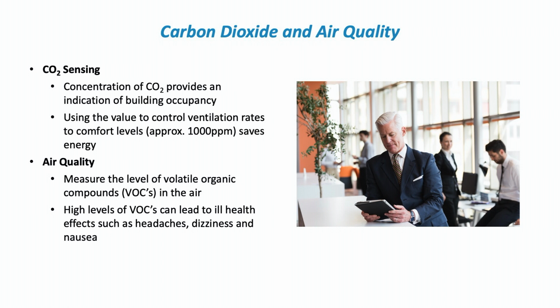CO2 sensing and air quality, so the quality of the air in our buildings. I have got just a little further example in the next slide here, but carbon dioxide is a good indicator of how many people are in a building. If we are controlling the ventilation properly, then we should see a parts per million value of CO2 in the space of around about 1,000. So there should be 1,000 parts CO2 per million of air.